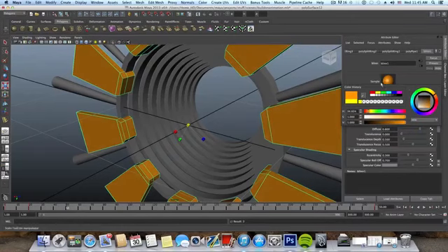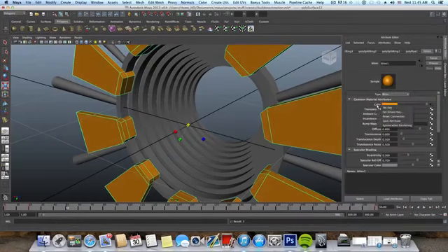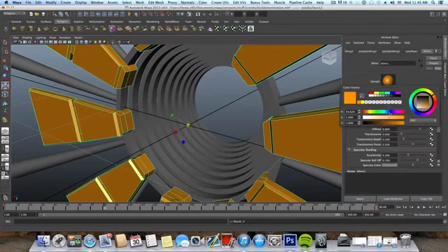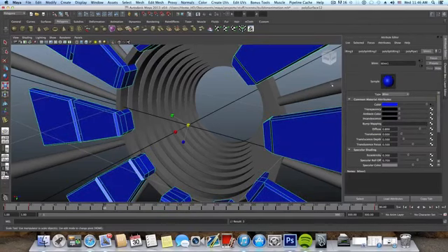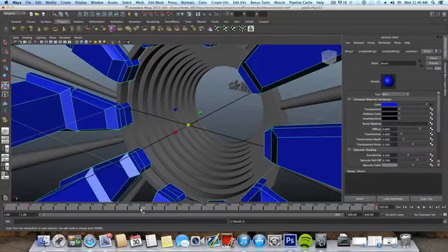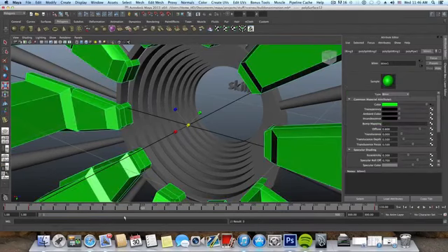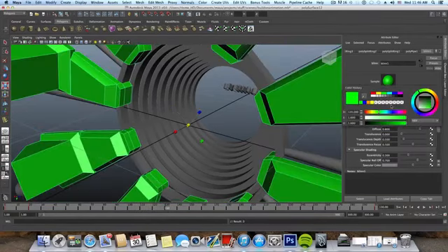You won't see any red marks here, but you just need to trust me on this one. So choose the color blue and then right click, set key on 80, continue to 110, choose a different color like green, and then right click, set key, jump to 130, change the color to something like red, and set key, I'm always confusing.